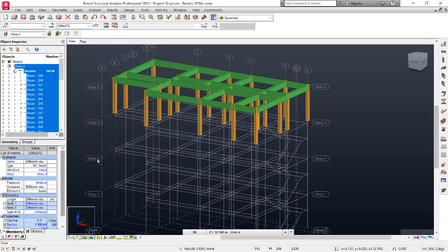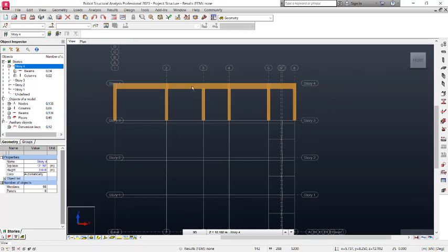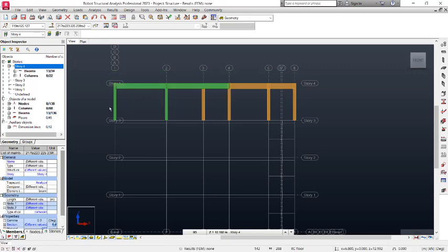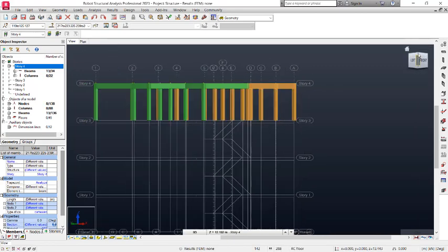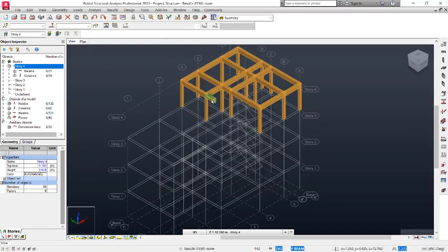All right, so what we want to do now is how we can remove some part of this roof beam and the columns, right? Because the structure is just like a penthouse, okay, a penthouse floor. So we get to the front, right? From these provisions, we wouldn't have any members from these provisions, right? So we have to select this, and then you can orbit it this way. Okay, so we get rid of these beams by clicking on the delete option right there. Okay, so we can as well get rid of this one.